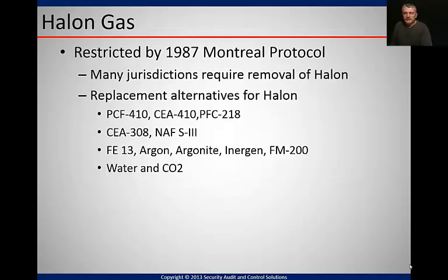Now, halon gas has been restricted by the 1987 Montreal Protocol. The reason for that is that halon gas contains what they call a CFC, or chlorofluorocarbon, which supposedly attacks the ozone, which is O3. Many jurisdictions require removal of halon, and there's a replacement alternative for halon. What you need to do is look at a couple of them, learn them off by heart, and see if they are mentioned, and what they do as well.